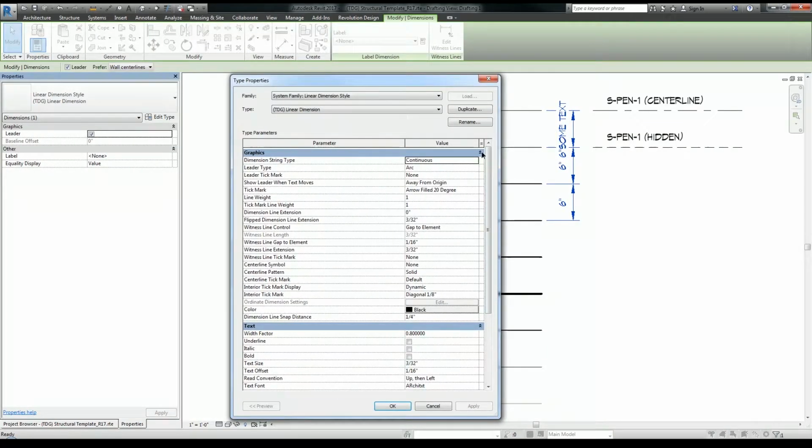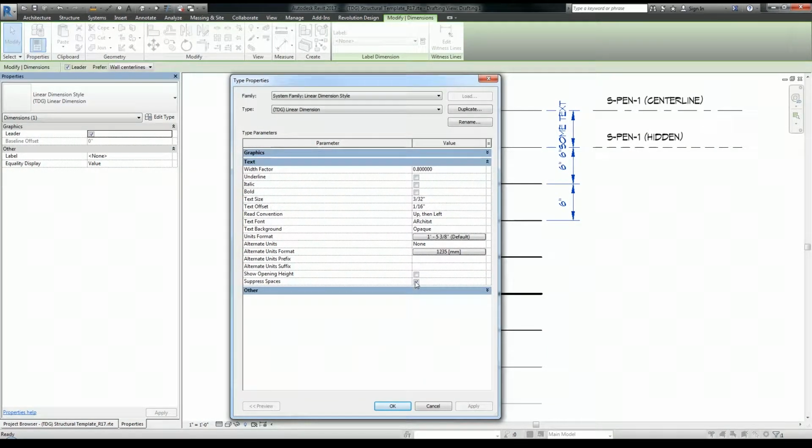Going back to this suppress spaces option, if I were to uncheck that, click apply, you see that the value is now 6 inches, space, some space text. Click it again, hit apply. You can see that it suppressed the automatic space in between the 6 inches and the some space text value. You notice that it did not suppress the space that we put in between some and text. This suppress spaces option is only for automatic spaces. It does not suppress any manual spaces that are put in.